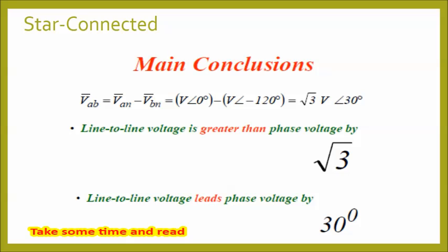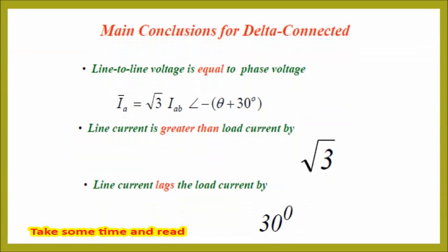We take our measurements in two separate ways: number 1, phase to neutral, or number 2, phase to phase, also known as line to line. Phase to neutral means we will observe all our required readings between the related phase and the neutral. Line to line means we will observe our readings between the related phase and the next phase.